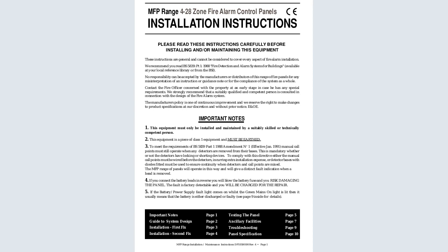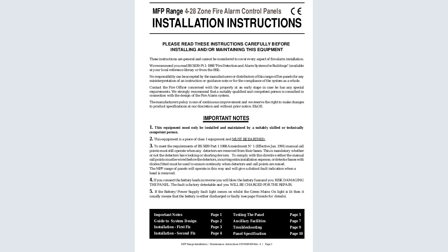If you connect the battery leads in reverse, you will blow the battery fuse and you risk damaging the panel. This fault is factory detectable and you will be chargeable for the repair.